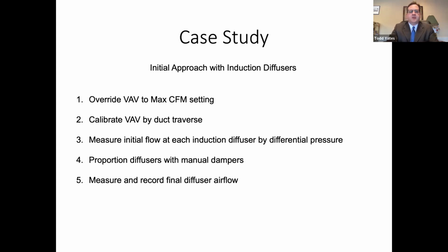So we thought it's going to be a bit tedious to have to take 10 differential pressures, move around, move the ladder. It's not like you can just walk through with a hood and measure each of these. You've got to move a ladder to each one. You've got to climb up, take the differential pressure. And even if you're doing what we did and putting that in a spreadsheet to make it simpler, it still takes a lot more time.